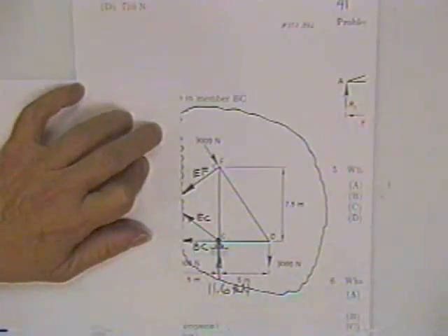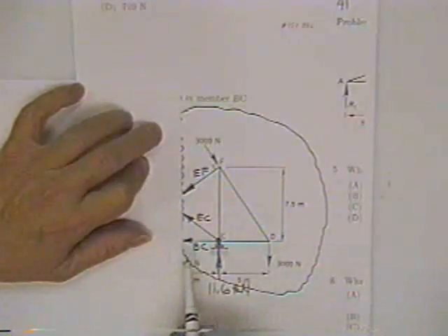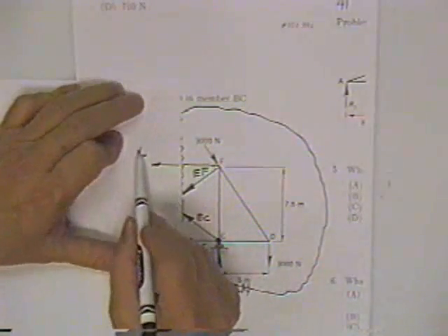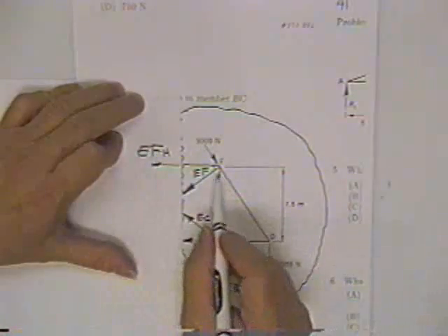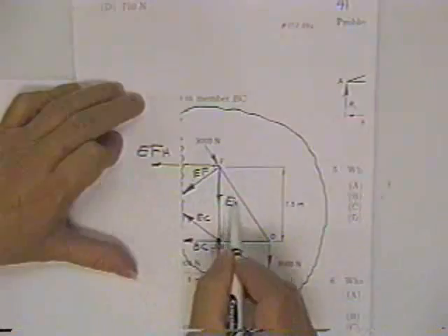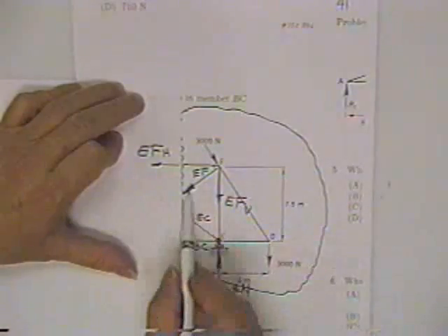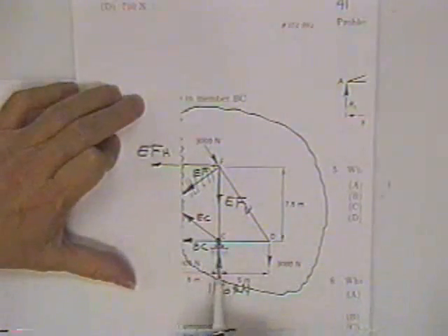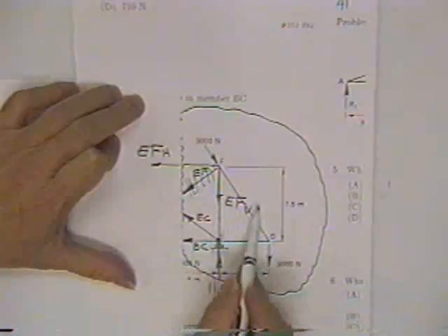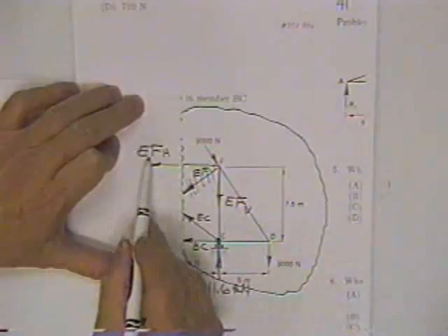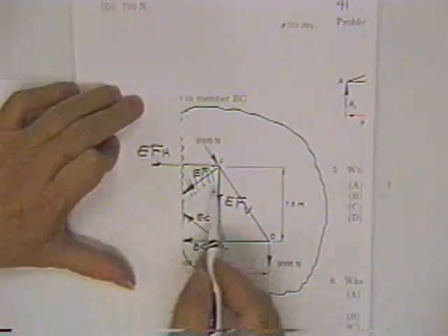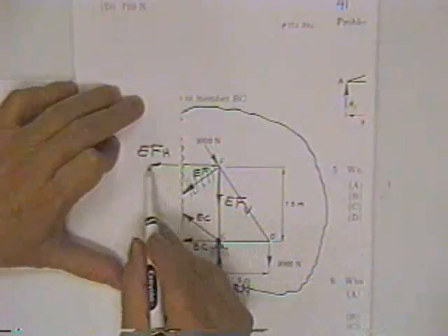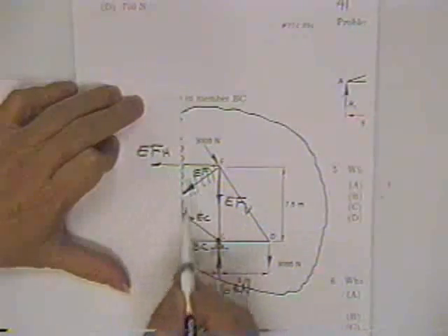Now you'll have to be a little careful with EF, because EF isn't going to have a nice moment arm. In order to get EF, you'll have to show EF horizontal, go ahead and break it up into two pieces, EF horizontal and EF vertical. When you do that, throw away the original EF and sum moments about C. You'll notice that's pretty nifty. EF vertical goes through C. All you have left is EF horizontal. Knowing EF horizontal, you can turn it into EF, because EF times the cosine of this angle has to be EF horizontal. You can work backwards to get EF.